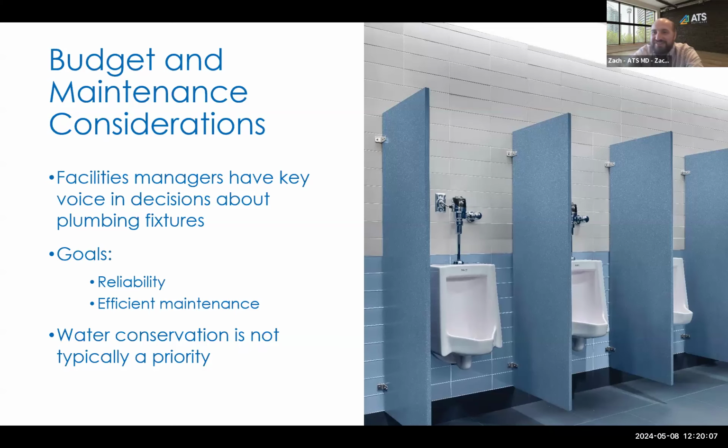We're not doing a healthcare facility, so we don't need the 20-minute run. Although that was helpful for a hospital project I was working on just a couple of weeks ago, where a similar sensor operated faucet can do a 10-minute runtime purge. If you're interested in that and you haven't attended our healthcare ATS University, please feel free to go watch the previous recording. The healthcare and hospital world has no care for water conservation, for very different reasons, and they're quite valid.